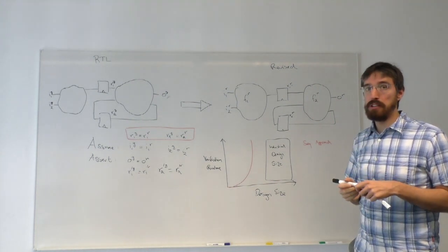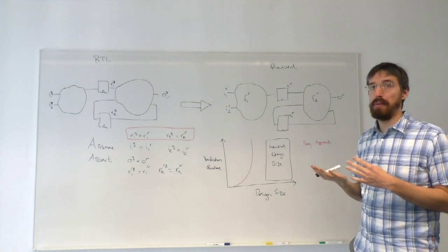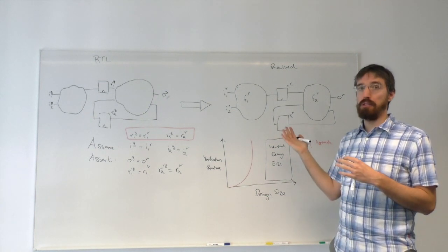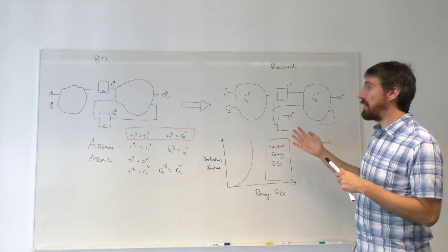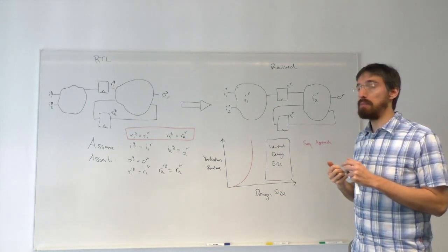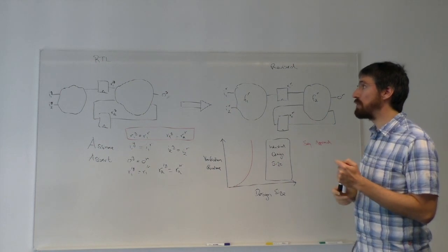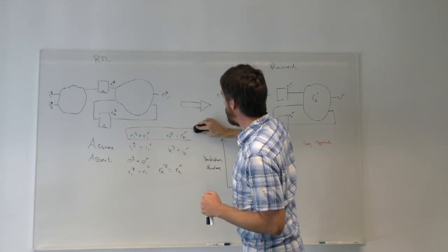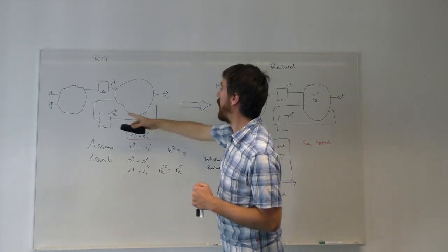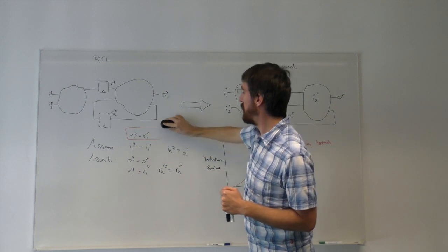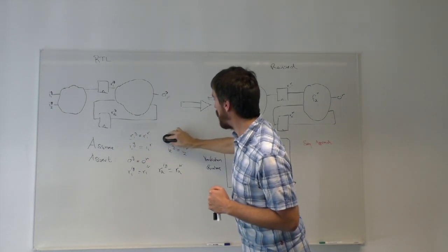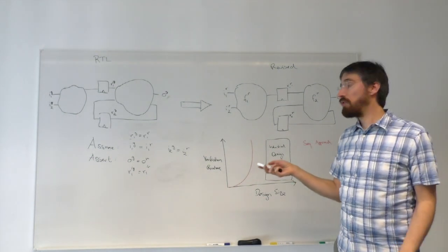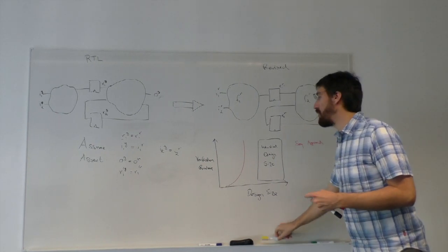The verification tool will generally try to figure out most of this correspondence by itself. But in general, it helps, and it may be necessary, to add parts to the inductive invariant manually too. The inductive invariant may not be complete, which may be the case in practice, because the transformation the implementation tool is doing is not fully understood. Then you can end up in a situation where this inductive invariant, which I wrote down, is not complete. Let's assume that R1 is found, but R2 is not. In this case, you would end up with an inductive invariant which is just the R1 part, and you would also lose this assertion here. You would still have hints to the prover, so it would be better than the sequential approach, but it would not be as scalable.